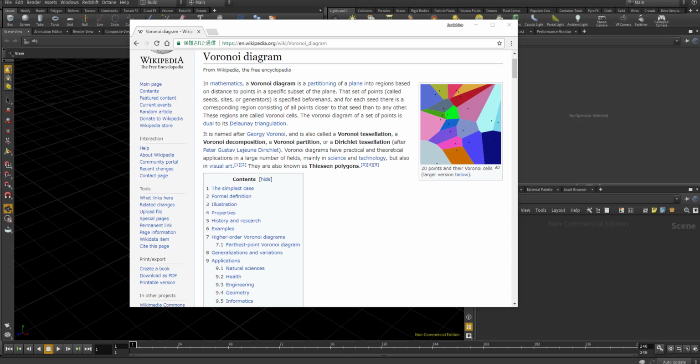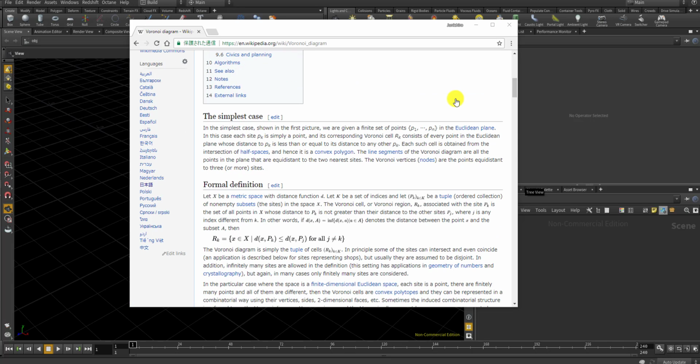In this video I'm gonna show you how you can make Voronoi partitions, which means just getting the edge of the Voronoi cells, using the volume function, volumes in Houdini. But that itself can be done really easily using the noise function called the Worley function, which I think you can use from the volume VOP.